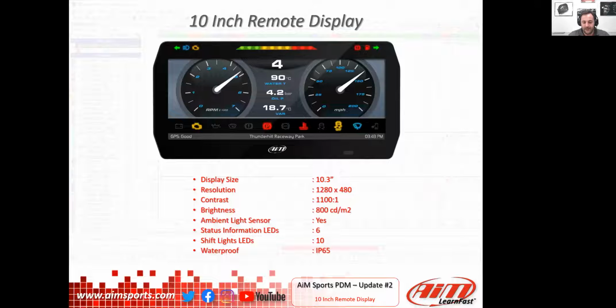Up to now it is not allowed to connect directly to the PDM to display it, but you can set, like we discussed some minutes ago, another display with a CAN connection to the PDM. And in that case, you can put 1, 2, 3, 4, or a number that you want to display and manage different display formats, different information displayed on the display. So this could be very, very useful for a situation, for example, in a rally race where the co-pilot has to show some information and the pilot has to view other information. So you can do it very, very easily.